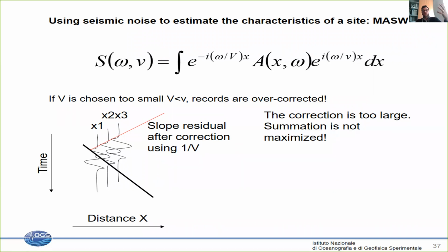For an absurd case, I will have a seismogram with waves arriving first at the farthest site, then at the nearby site. So what will happen if I now stack these results? For sure, I will not have a maximum. You see, I can stack a maximum with a minimum, maximum, minimum, so this will be nearly equal to 0. So it will not work.